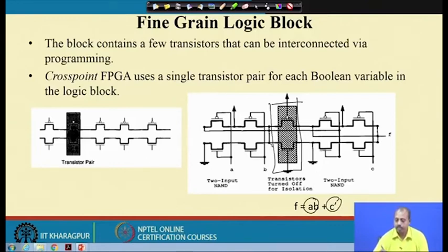So, you see that this is an n type transistor and I have connected its gate to ground, and the p type transistor I have connected its gate to high. As a result both the transistors are off. So, this establishes an isolation between this AB term and the C term, and so the logic is transferred from one side to another by means of these interconnects that we have between these transistor arrays, but otherwise the transistors are not connected to each other because of the isolation stage.